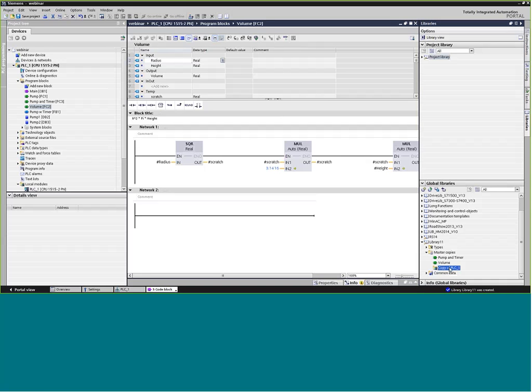So if we put an Ethernet module out on the I/O bus next to a 300, it's going to communicate over that K-bus. At the time, in the mid-90s, when the S7-300 came out, we were still talking about 9600 baud and so forth. The backplane K-bus is 187.5 kilobits per second. So that's actually, at the time, fairly fast.